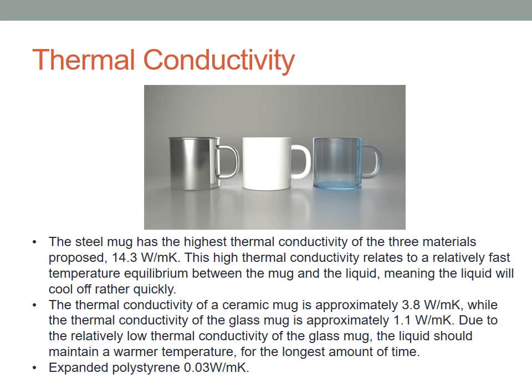Let's say you're camping, and you're using a steel mug. When you pour boiling hot water into it, if you were to wrap your 2 hands around it to warm them, you would quickly burn your hand, because a huge amount of the heat energy flowing from the boiling hot water is going through the steel and into your hands at a very, very high rate. That's because steel has a thermal conductivity of 14.3 watts per meter Kelvin.